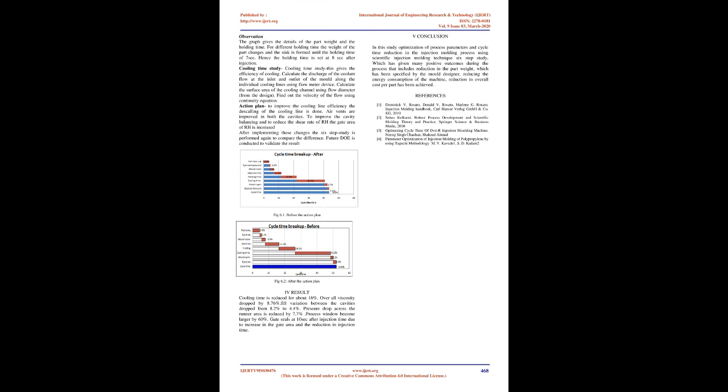The descaling of the cooling line is done. Air vents are improved in both the cavities. To improve the cavity balancing and to reduce the shear rate of RH, the gate area of RH is increased.